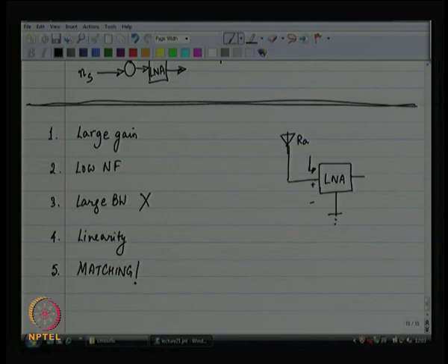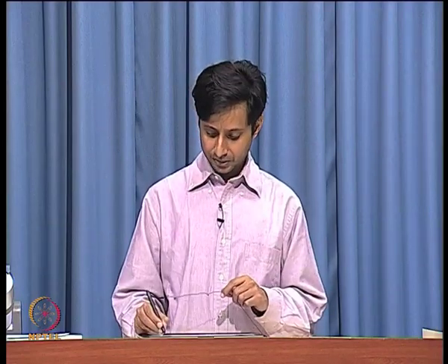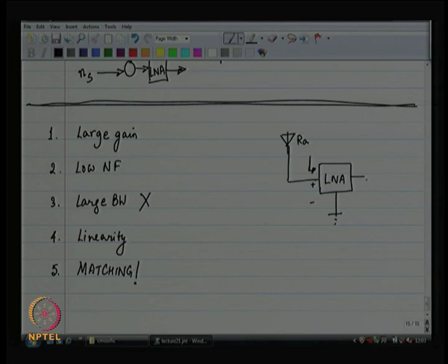So, you want to do maximum power transfer as far as the output is concerned too, right. So, both sides you need to do matching. Also, to conserve the shape of the signal, you would want to do matching over there.